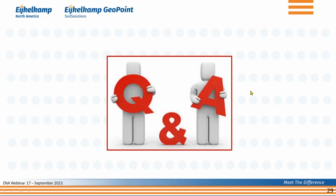And maybe that is a topic for a next webinar when we talk more about seismic CPT or downhole seismic testing. What you have to make clear is that the seismic wave does not travel in a straight line. If you assume that it travels in a straight line, it doesn't make any difference whether the results are obtained with CPT or DMT. You need to make sure that you come up with the right ray path.